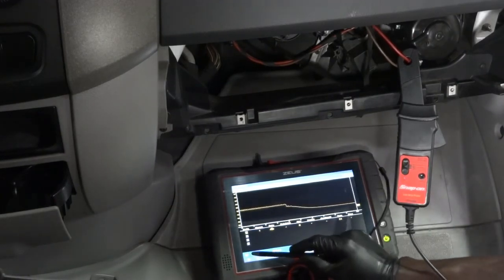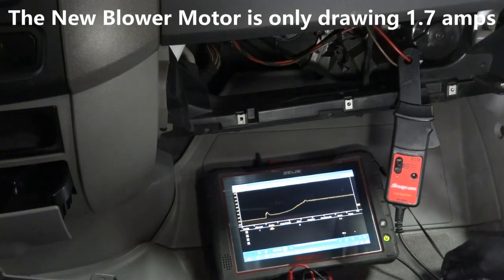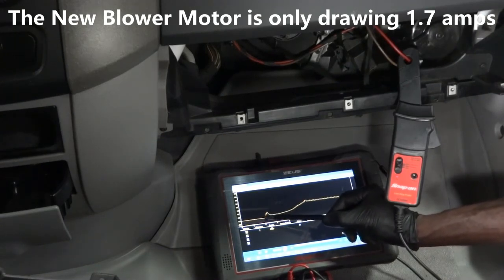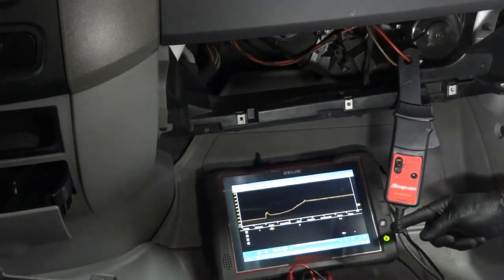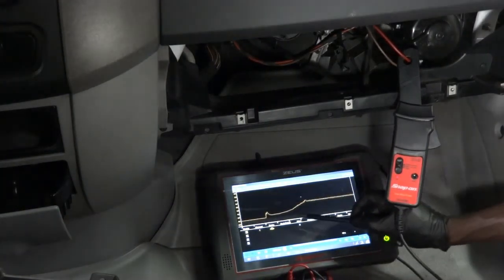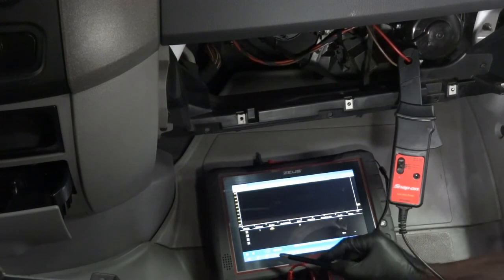Let me pause this. Can you guys tell the difference on this waveform? There's a huge difference between the one we were looking at first. With the new blower motor, did you guys see the increase in amperage here? But it's not a huge line that went all the way up to 5 amps. Okay, it went up a little bit to about half an amp, and then as I started increasing the blower speed, the amperage also started increasing accordingly. All right, so this is definitely a fix.